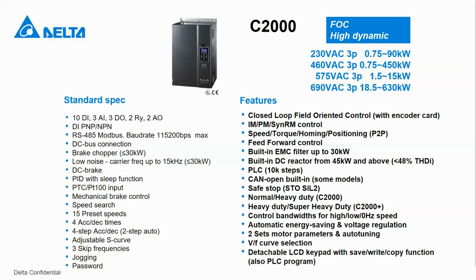You can connect the keypad to other drives and then move it to a different drive. The keypad also supports user-designed screens, similar to a mini HMI or a text panel, and that can access different addresses in the drive or in the built-in PLC. And later on today, I will show you some functions related to positioning and to synchronization.